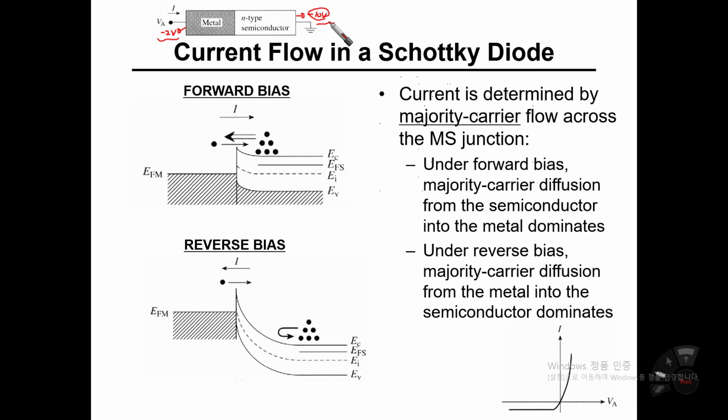Why? The basic assumption behind that statement is that the semiconductor is grounded. So we should watch out for what kind of voltage has been applied onto the semiconductor part. Once the semiconductor part is grounded, then positive bias means forward bias, and negative bias onto the metal side means reverse bias. That's true. However, without any knowledge of how much voltage is applied onto the semiconductor part, we cannot claim that positive bias is identical to forward bias, or that negative bias onto the metal is reverse bias.